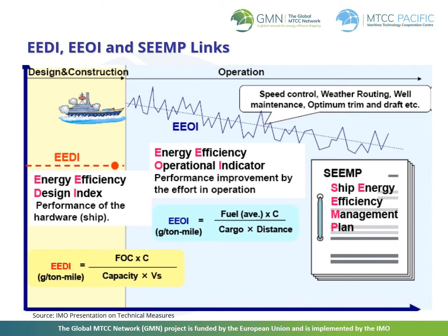The SEEMP is a management tool and establishes a mechanism for ship operators to improve the energy efficiency of ships during their operational life cycle. SEEMP follows the steps of a continuous improvement management cycle. This is planning, implementation, monitoring, and review of energy efficiency measures.